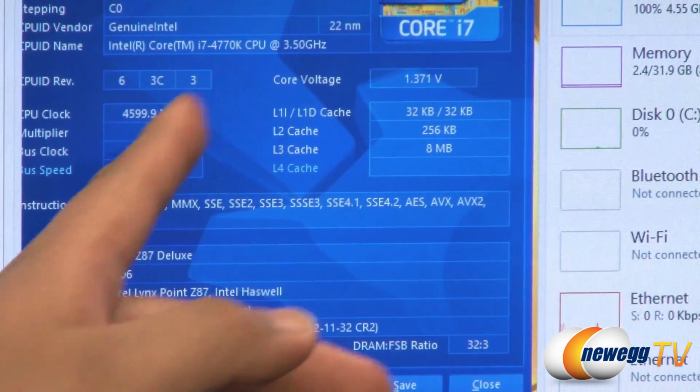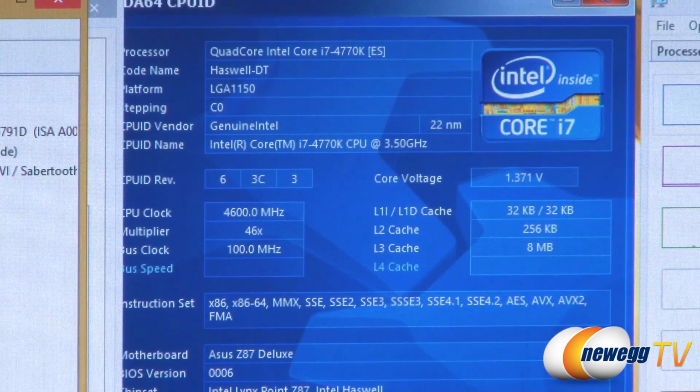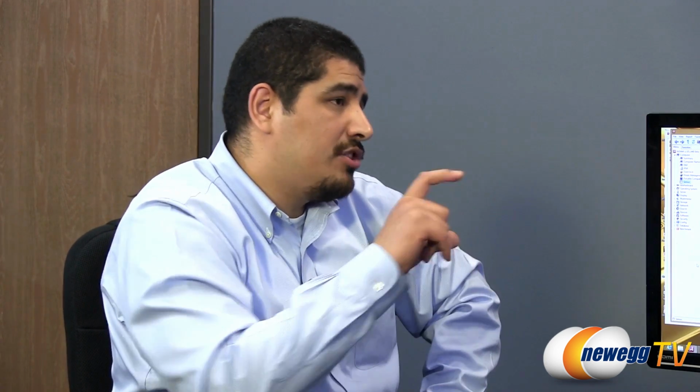You can see right here, now the voltage is dropping down because at some points we're now hitting a throttle point. Even with that solution, we cannot control that high level voltage. So this is where we really stress and advocate that if you're going to focus on a manual stress testing application, you're going to want to go in a different direction, which might be to manually tune your voltage, but you're going to be compromising the overall better efficiency, the lower power consumption, and the extended lifespan. This is part of the reason why we choose an adaptive voltage, because we can give you that high level of performance that is going to work for 95% of you, because when you're setting up a system and running it, you're not running your CPU 100% of the time.